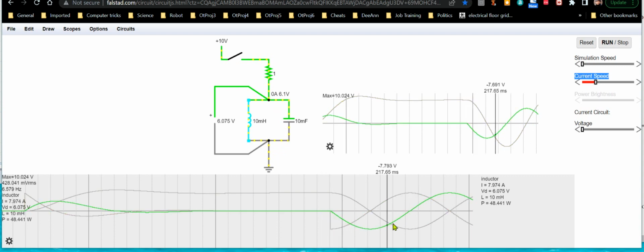But yeah, this capacitor is discharging from here to here as the inductor is charging. You can see the indication of an inductor charging is its current increasing, which it does right up until here. So the inductor's current is increasing, it's just in the opposite direction of what you see here. It's flowing this way, basically. So that's why you have positive current flowing from the capacitor, but negative current flowing into the inductor.